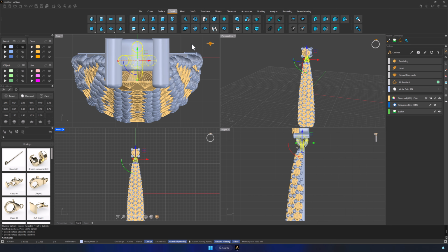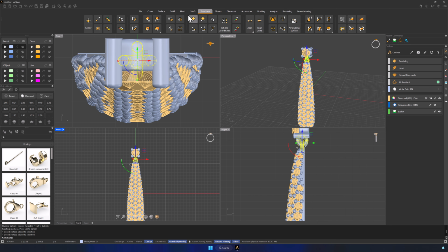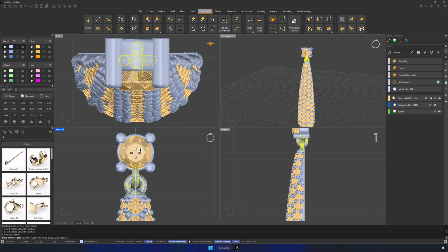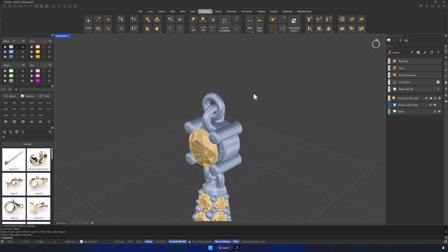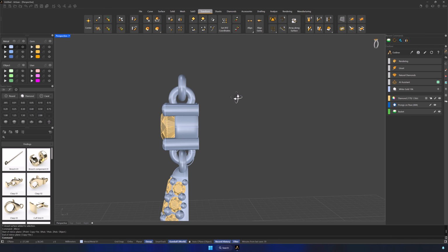Select the rings, go to the Transform tab, and use the Mirror command. With OSNAP active, select the right end of the basket and then the opposite end to create a copy at the top. From the perspective view, adjust the basket and gem along the Y-axis so the rings are more or less centered on the basket rail.